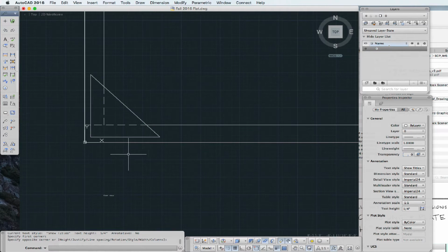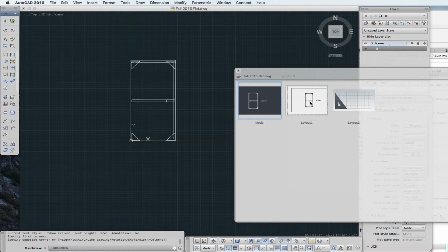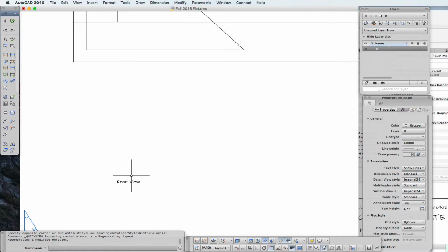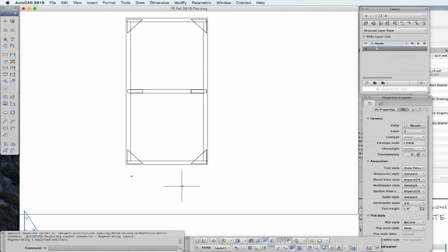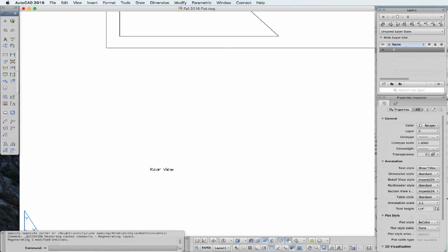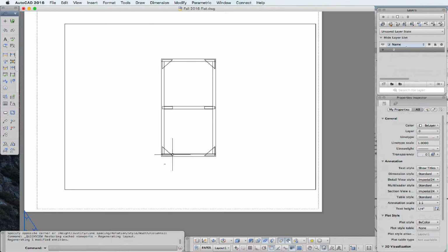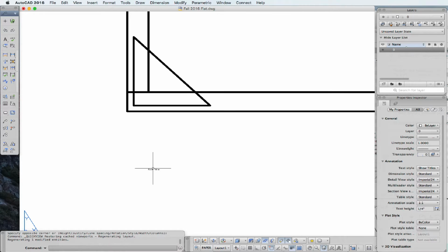So obviously, when we look at this in paper space, let's take a look at this in paper space for a second. Our layout here, it's going to be tiny. So we want it to print out at 3/16, which means we need to do a little bit of math. If we want these letters to be 3/16 in the printout, and I plan on printing my drawings out in 1/2 inch scale, it means that this is going to want to be 3/16 on this page.